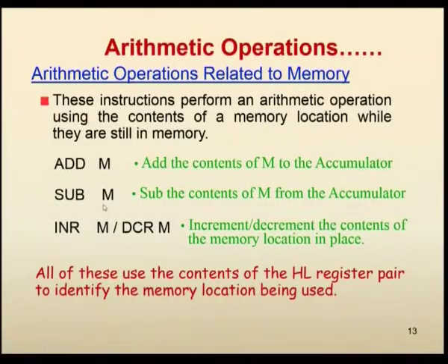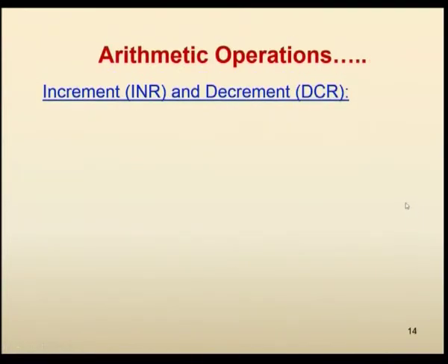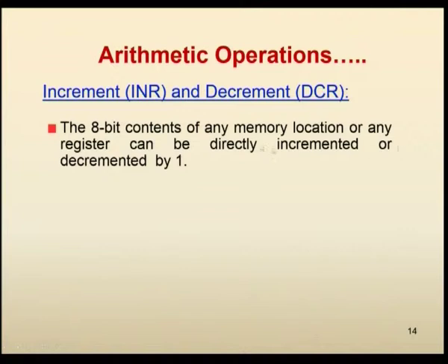After loading the HL register pair, of course, by using the data transfer instruction, then only you have to give any of these instructions. This is very important. Of course, all these things we will see when we go through the many programming examples. Again, you can increment and decrement the contents of the memory location also.